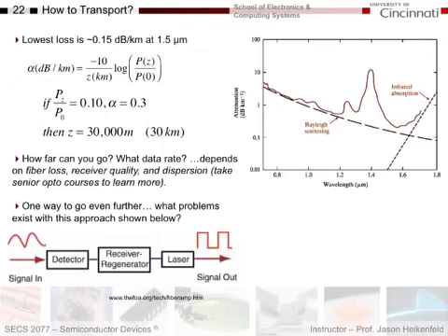So, what type of material do we use for optical fibers? Well, it's interesting to note that we use the same type of material that we use for computing, except it's oxidized. So you use silicon dioxide for optical fibers. The reason why is if you look at attenuation versus wavelength, silicon dioxide has very low attenuation at 1.5 microns and around 1.3 microns as well.